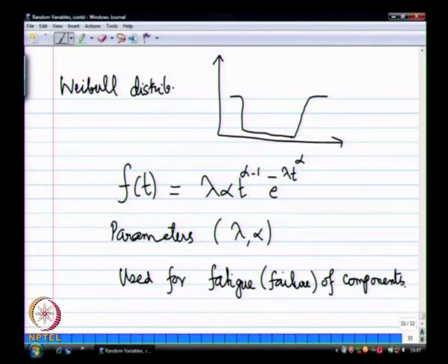If you look at a PC, it has so many things, your memory, CPU and so on, then very often the first thing to go is your hard drive, and you simply have to replace that, which is okay on a desktop system, but in the middle of your flight if your hard drive goes off, you cannot hunt for a hard drive and replace that. So based on this distribution they will plan the redundancy in the system, how to increase reliability and so on.